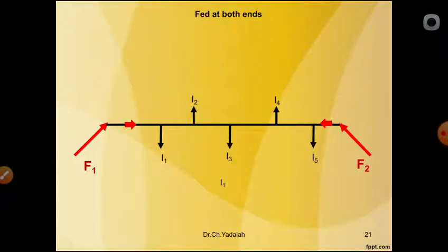So what will happen in the first case? Only one feed at the starting. So the consumers connected near it will get high voltage, and their bulb will glow bright. The consumer connected away from the source, at the very extreme right side, may not get his tube light to glow in his house.